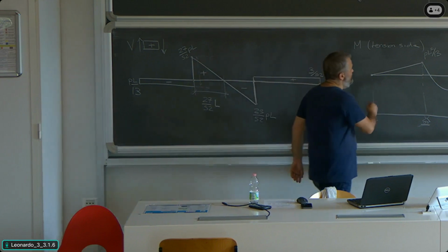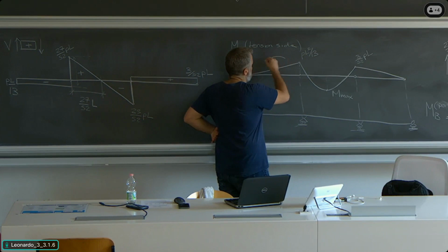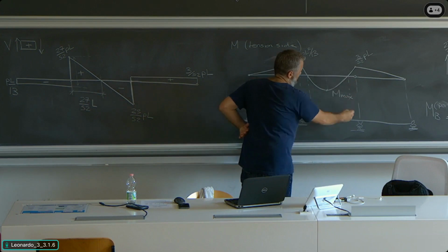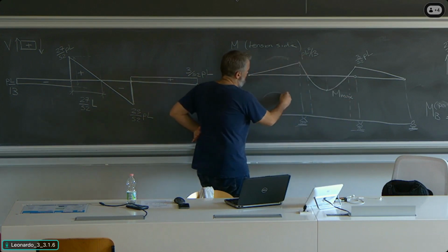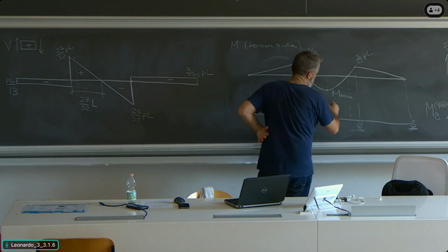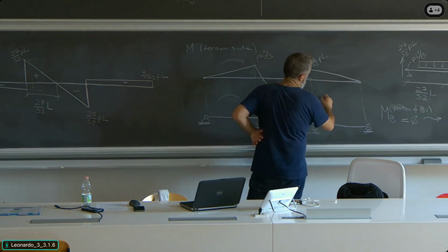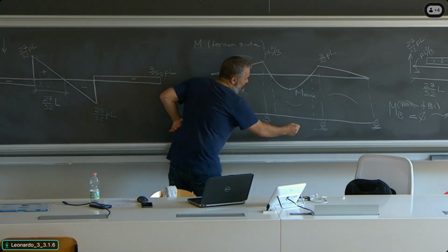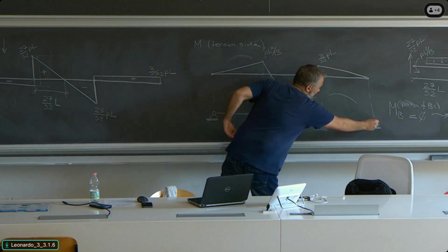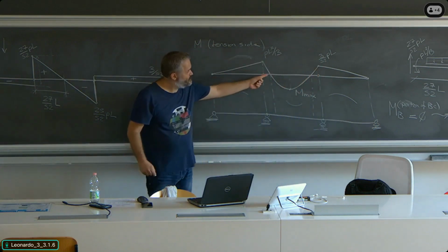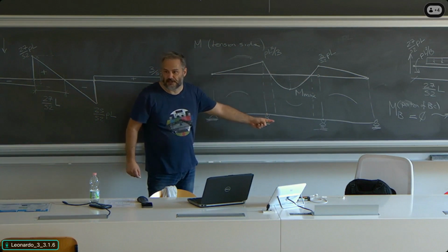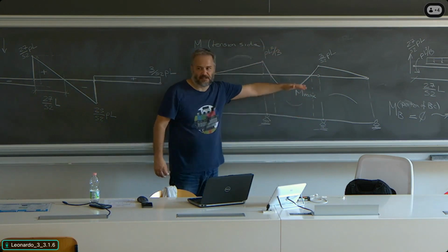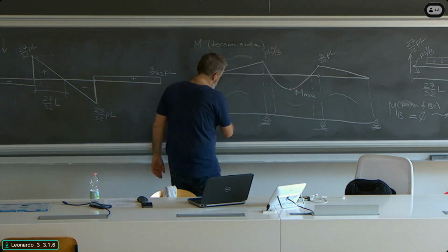We know that we have a curvature which is like this, where the bending moment is negative. So again, where the bending moment is negative, curvature looks like this. Where the bending moment is positive, curvature looks like this. The deformed shape should pass through the points of the supports, and there will be contraflexure points where the bending moment is 0. Putting this all together and remembering that this span here, the center span, is loaded, we have something which looks like this.